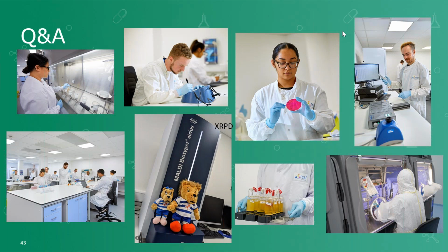But if you're running a WFI system and you're in the business of making sterile medicines, so you take the highest requirements, then you need to be doing, in my mind, supplies and return every day, source tank every day, and then at least a series of representative water outlets every day, and then maybe complete the entire cycle of water points within, say, a 7-day period.